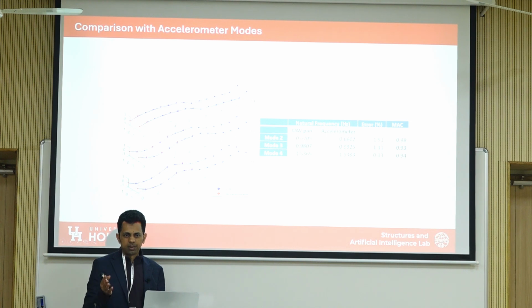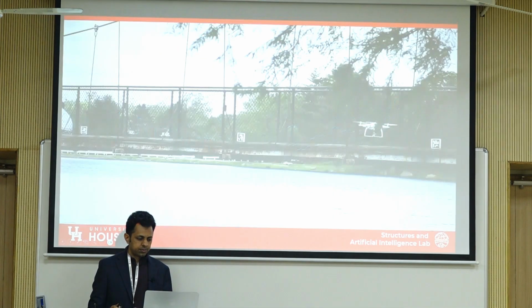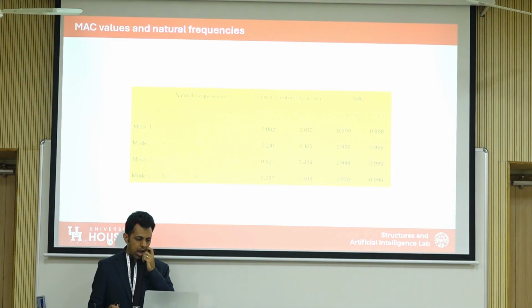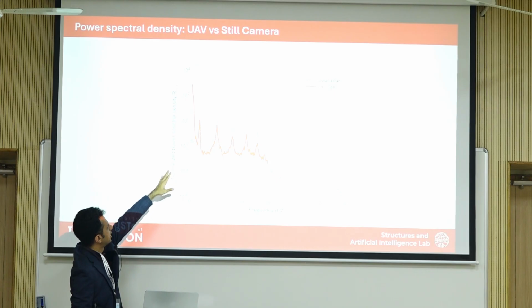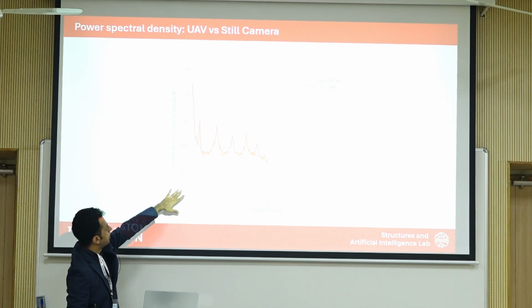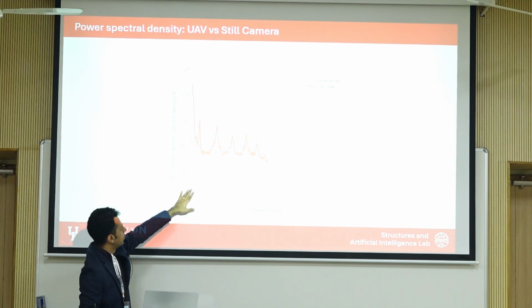And then you see what is the drone, because there's going to be a clear cutoff. So you can just measure the frequency from the signal that you have, because like I showed you here, you can see that there's some peak at the left, and then you have your structure frequencies.